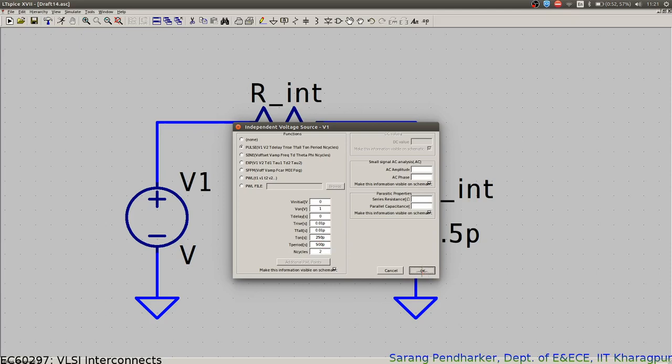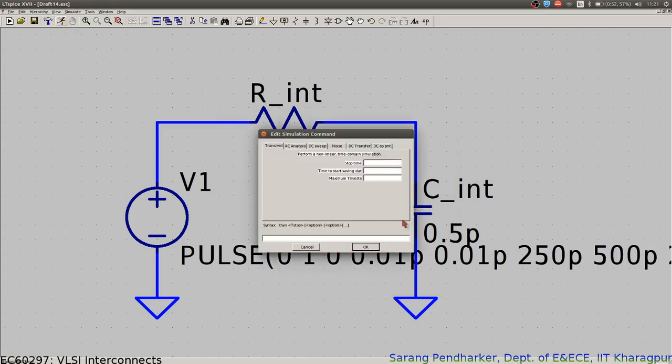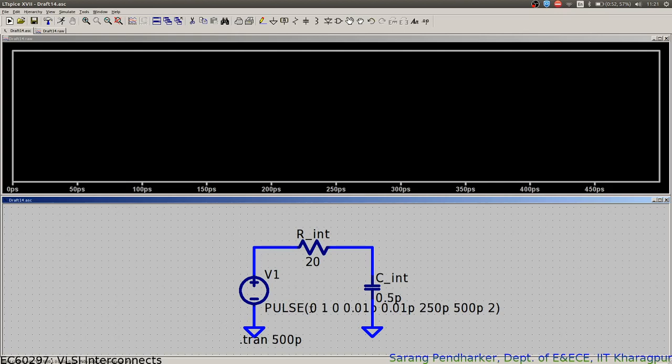take to be. So now I defined my input voltage. When I run it for the first time, it will also ask me for the stop time, for how long should this simulator run. So here I just want it to run for 500 picoseconds. So this is what comes. So yeah, I have simulated it, and once I simulated, some raw things come here. The time axis goes till 500.